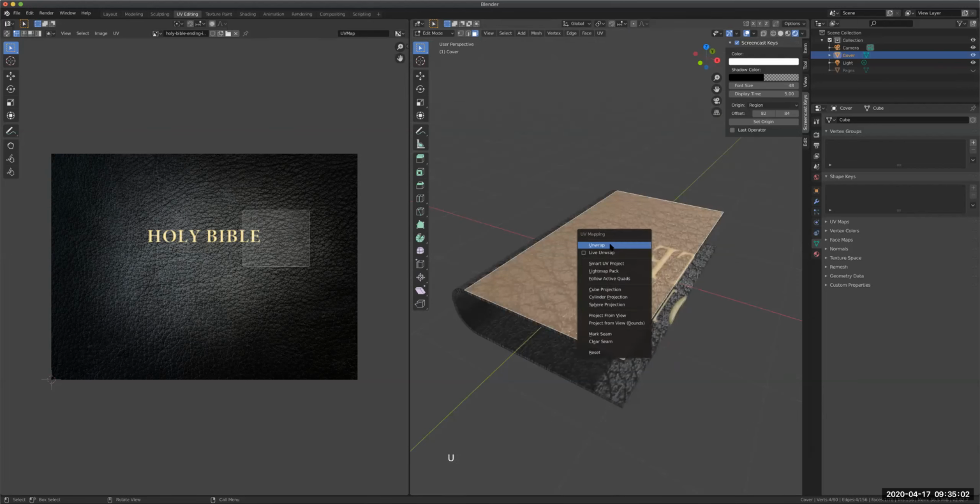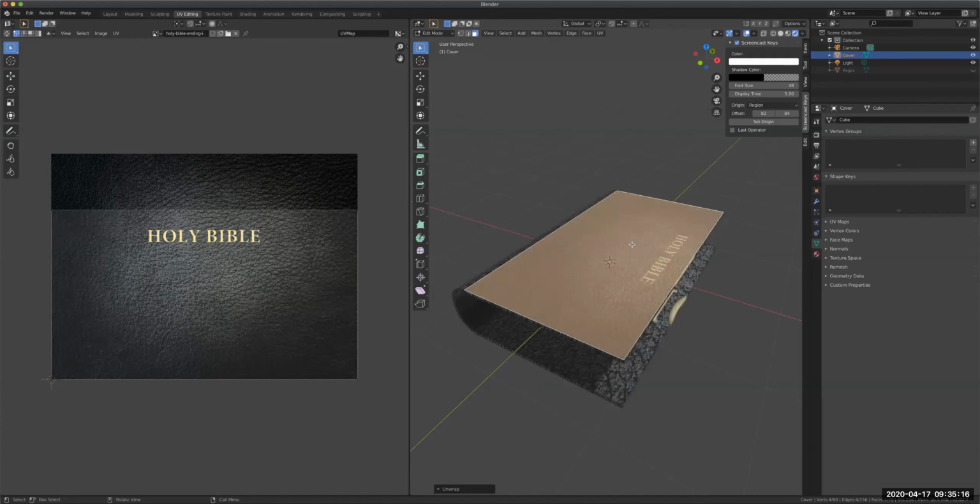We're simplifying this, so we're going to be applying those sides specifically to particular locations. So we're just going to use Unwrap right here. Not Smart UV Project or anything, just simply Unwrap. So I'm going to click that. Okay, as you can see, the orientation is wrong, but at least it gave us the proportion for this one. So here I'm going to select all those by dragging, or I can press A to select them all.